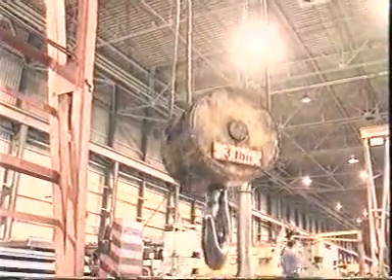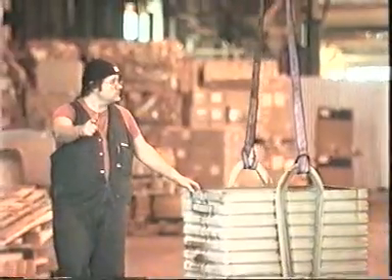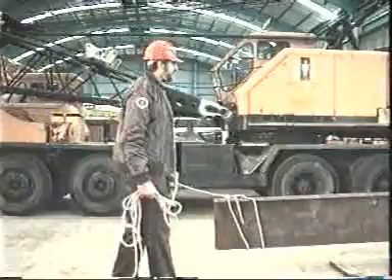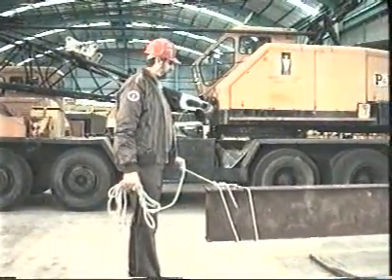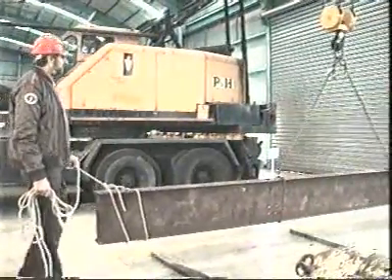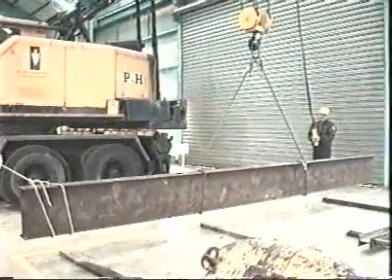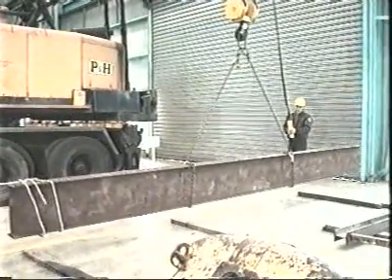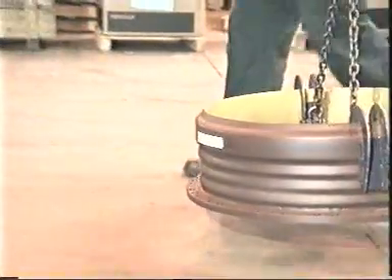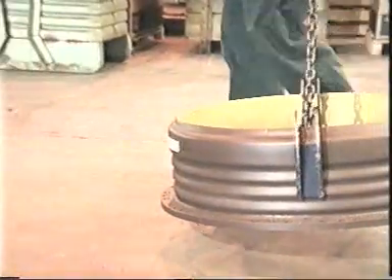Never place the hook block on the ground or the load. This releases tension on the hoist rope and can result in the rope bird caging on the winch drum. When traveling with the load suspended, acceleration and braking motion should be applied gently to minimize load swing. Tag lines can also be used to prevent pendulum motion of the load and enable the crane chaser to keep a safe distance. Remember to travel with the load as close to the ground as possible and keep your speed to a minimum.